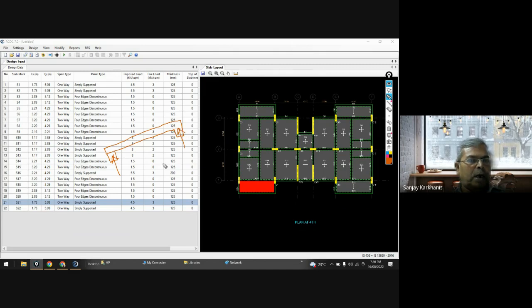Okay, and if you see the bending moment diagram, then according to this support condition, you will have a bending moment diagram like this. That means you will have a span moment over here as maximum. How much? WL square by 8. Yes or no?